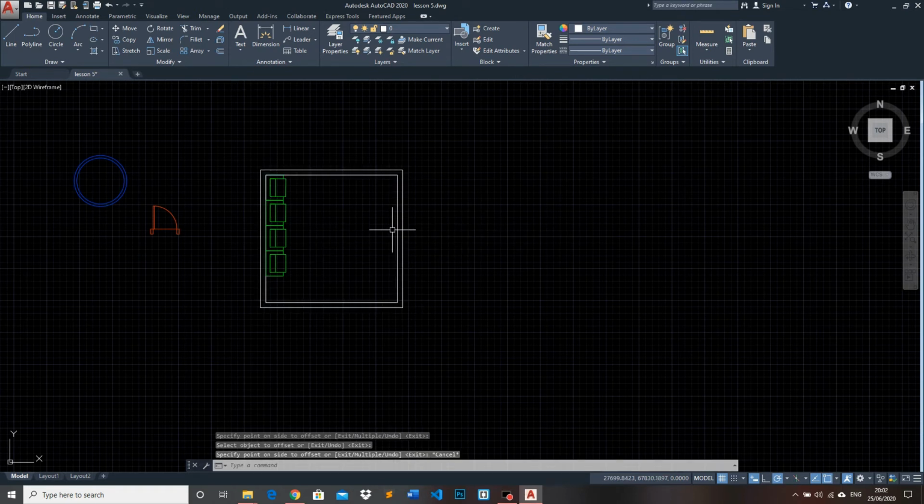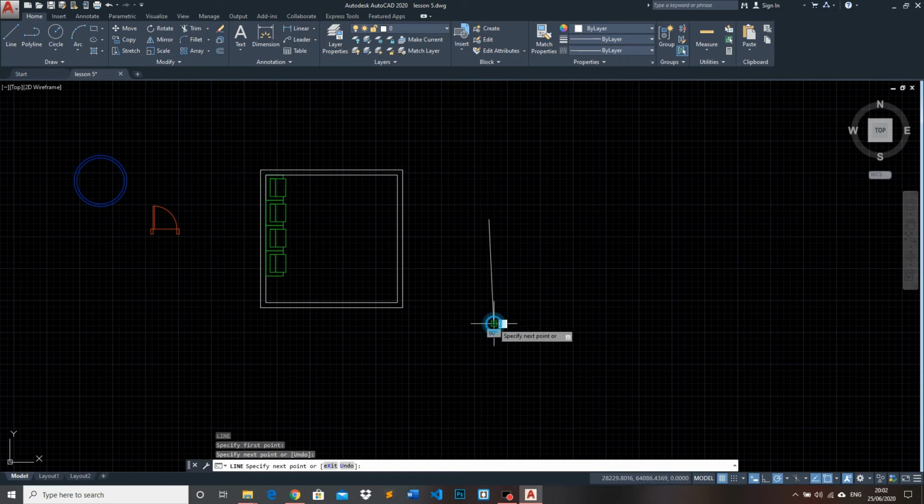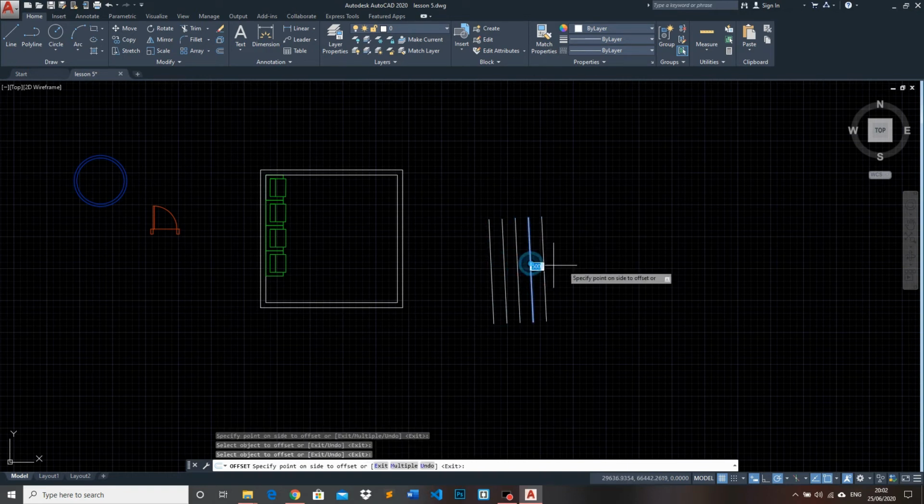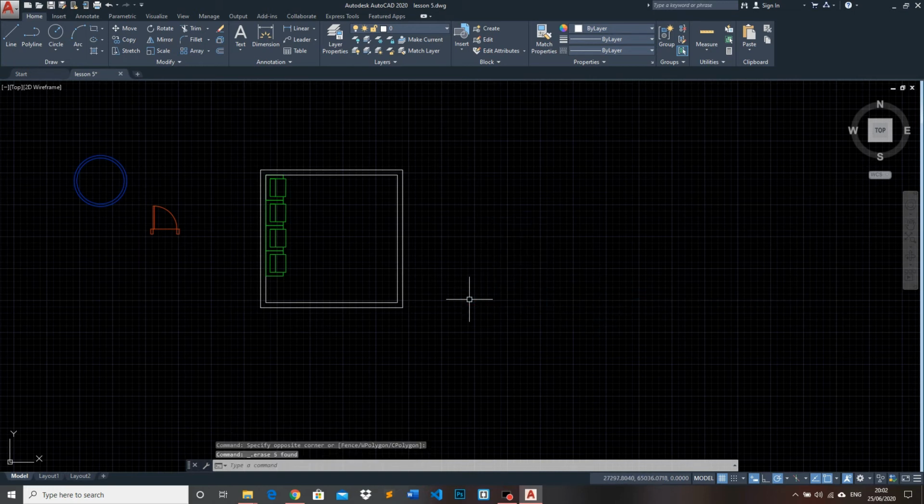If you want to create the wall inside, so that this is the only space that you have, you can do that. You can use this for lines. For example, if you want to create a line parallel to each other, you can use offset 500 like this. How much you want depends on you. You can use this command in various ways.